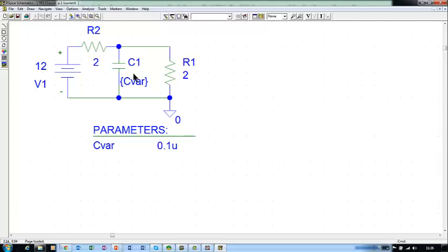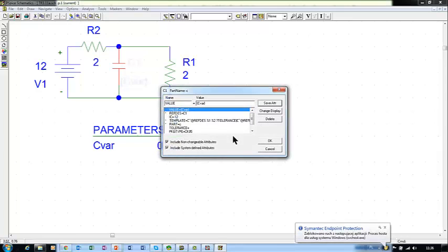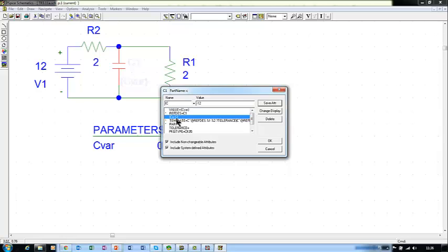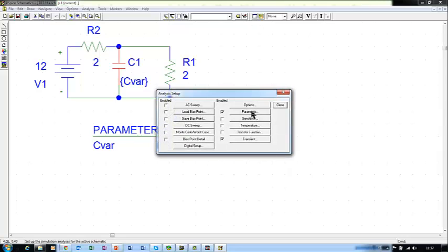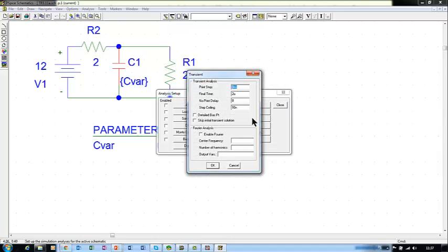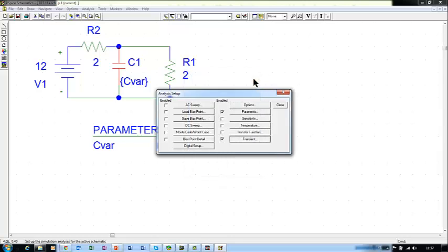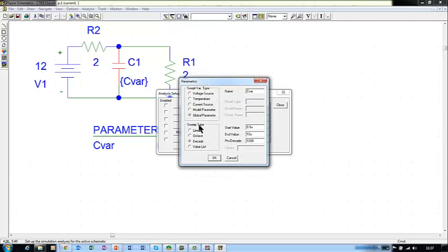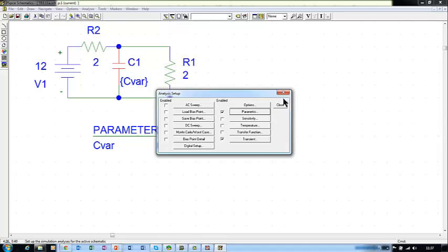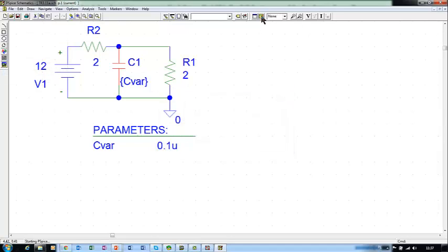Okay, circuit diagram already stored. So our capacitance, we have to double click here, and we have to set its value as C, a variable, but initial condition is minus 12. Attributes are saved. Also analysis setup, transient values. We've added a step ceiling this time, and sweep type decade from 0.1 to 10 microseconds, 1000 points per decade. After saving, we may run a simulation.